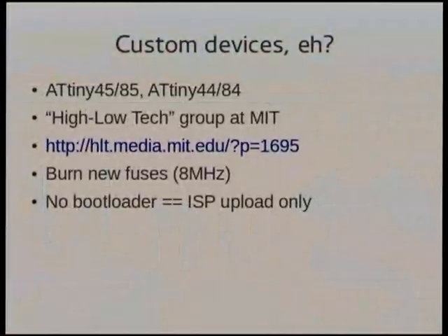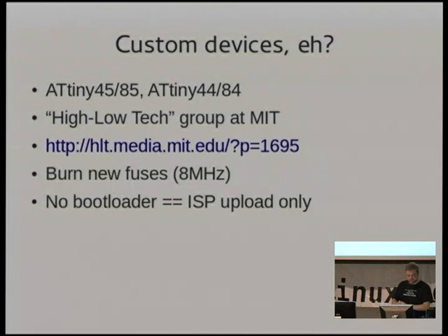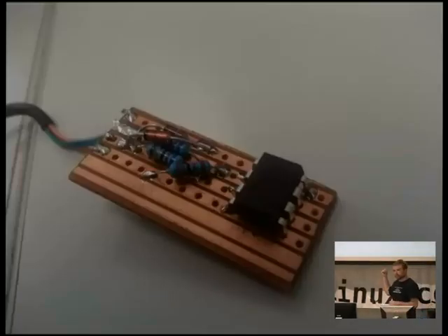If you burn a fuse that says this requires an external crystal, it won't boot without one because the clock counter for the CPU actually never advances. And that's the reason why you can't just take a chip out of an existing Arduino and try and run it in a breadboard without a crystal. Because you can't have a bootloader on the really, really small devices because of the limited amount of flash they have, you absolutely have to do an upload with an ISP. So that's an example of one that I did. Just ignore the really bad soldering because I was in a hurry. I'd like to blame my soldering iron for being too cold, but you know.